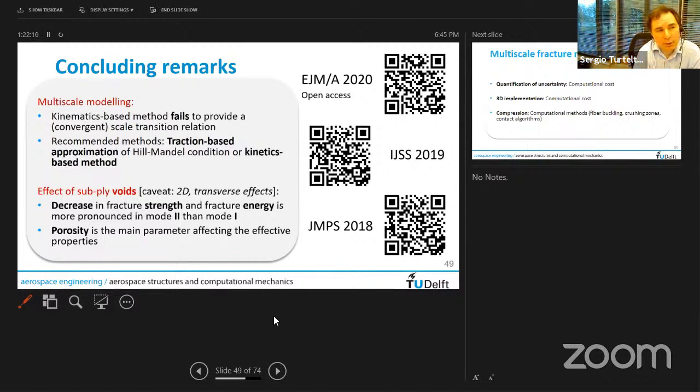The point that we are making in this work is that when it comes to fracture, we should not be thinking about an RVE, but rather a surface where the crack has localized. If you try to make the average on the volume, it will never converge. You need to make an average on the crack surface, which then brings me to the second part of your question, which is how do we connect the lower scale to the upper scale?